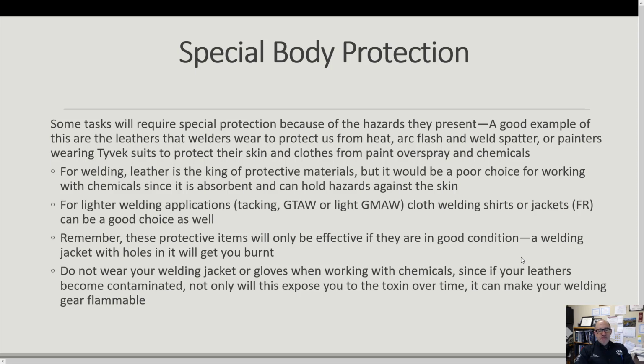So remember, these protective items will only be effective if they're in good condition. A welding jacket with holes in it will get you burnt. The holes develop where the maximum exposure is, which is usually the crook of your arm, places like that. So the holes are there for a reason, because that's where most of the sparks land. As the holes get bigger, more and more sparks get into you. And you will weld better when you're not getting burnt.